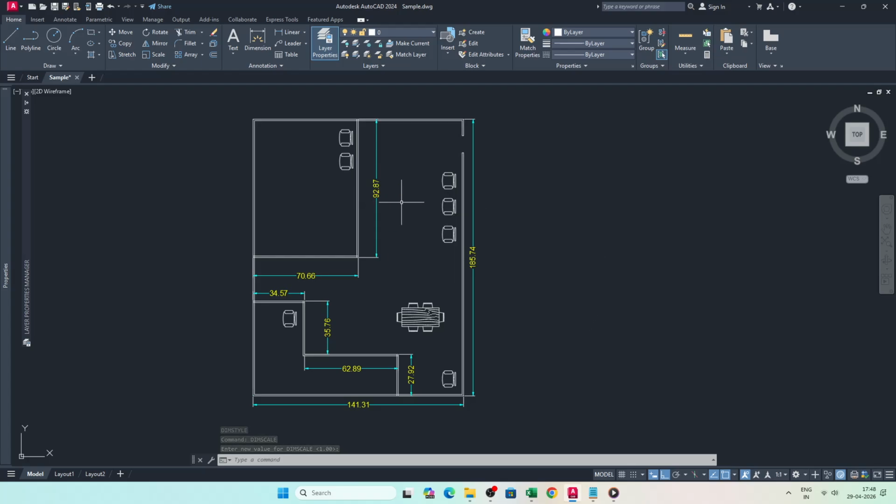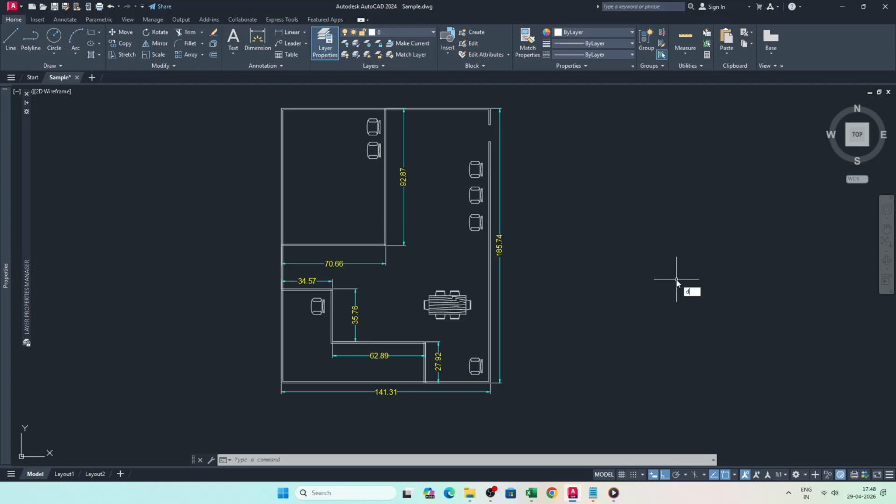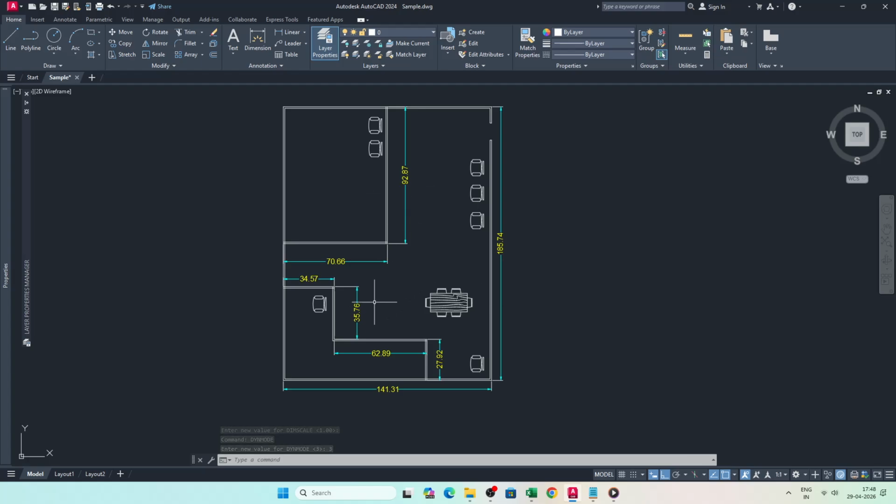Finally, if dimensions aren't previewing while you place them, check DYNMODE. Set it to 3 to enable both pointer and dimension input during placement. This doesn't change existing visibility, it just restores the live preview so you can see what you are doing as you work. Work through these checks and your dimensions should display reliably. That's all there is to it.